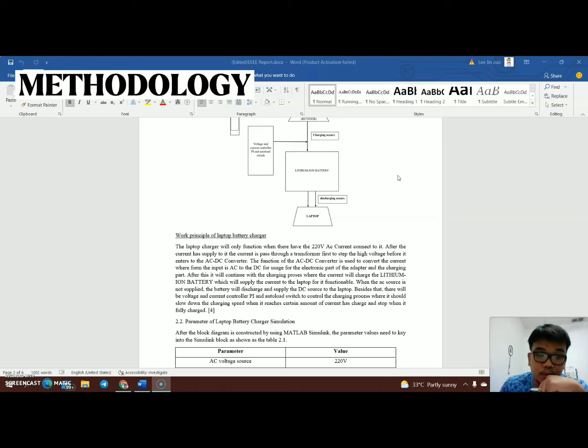Besides that, there will be voltage and current control PI and auto load switch to control the charging process, where it should slow down the charging speed when a certain amount of current has been charged, and stop when it's fully charged.